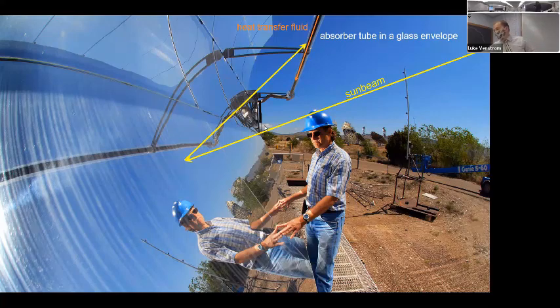You can see in your handout lots and lots of these parabolic trough collectors. Some of these parabolic trough systems get the temperature of the heat transfer fluid as high as 550 C. And then we take that high temperature and essentially use it to produce steam and drive a steam turbine and produce electricity. So in designing these things, you have to understand the internal flow convection heat transfer in order to size the tubes and get the temperatures that you want.